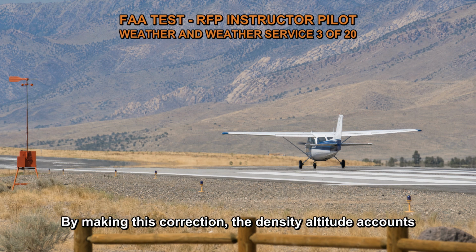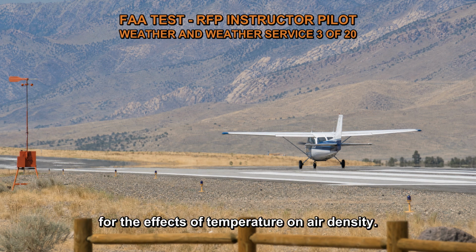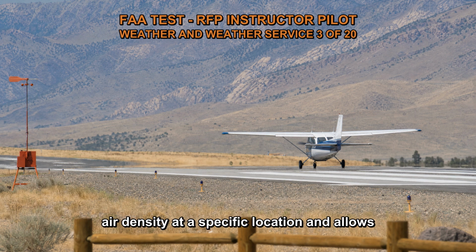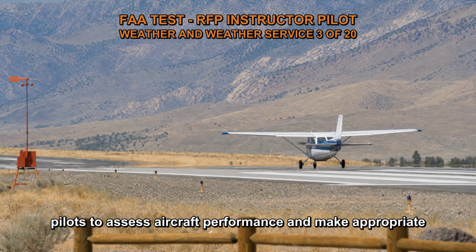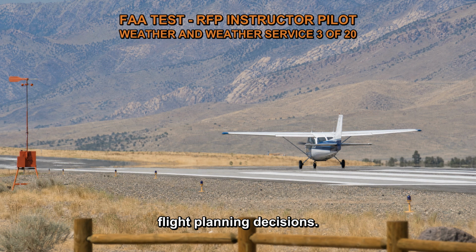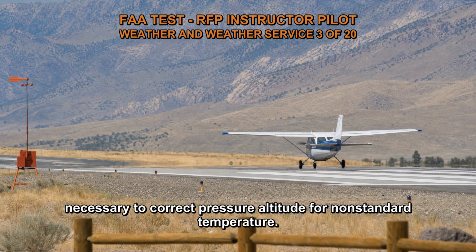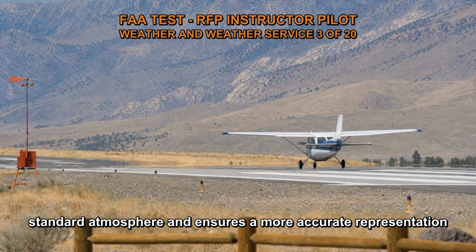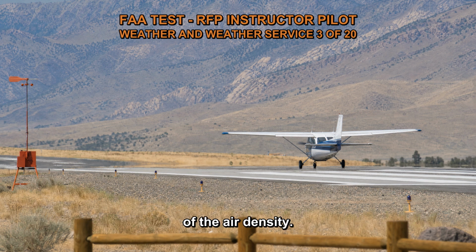By making this correction, the density altitude accounts for the effects of temperature on air density. It provides a more accurate representation of the air density at a specific location and allows pilots to assess aircraft performance and make appropriate flight planning decisions. In summary, to determine density altitude, it is necessary to correct pressure altitude for non-standard temperature. This correction accounts for temperature variations from the standard atmosphere and ensures a more accurate representation of the air density.